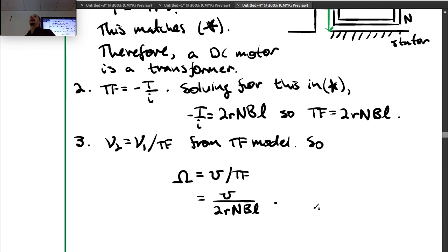Some motors can handle it. So really, it's not just a motor thing. You could have a motor that's got really nice, thick wires in there, and maybe some really good heat sinking out of the chassis. But if you run enough current, you can put too much current into any motor.